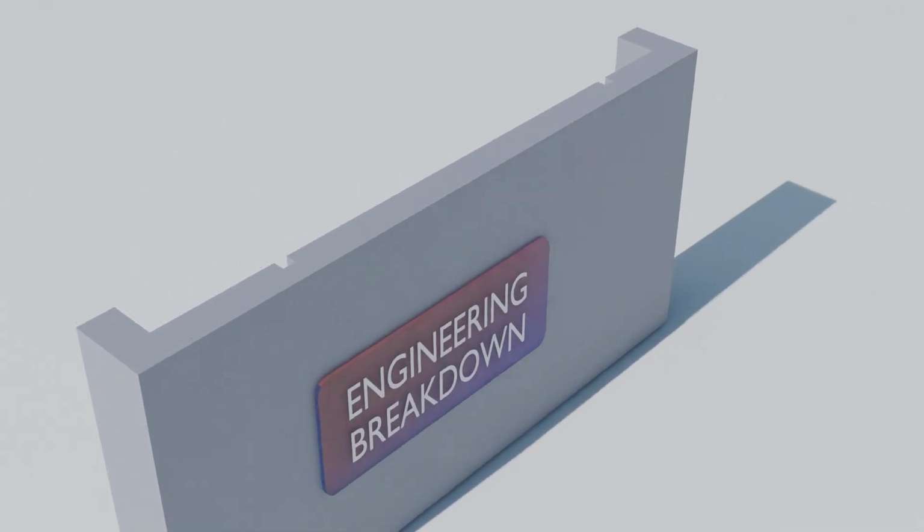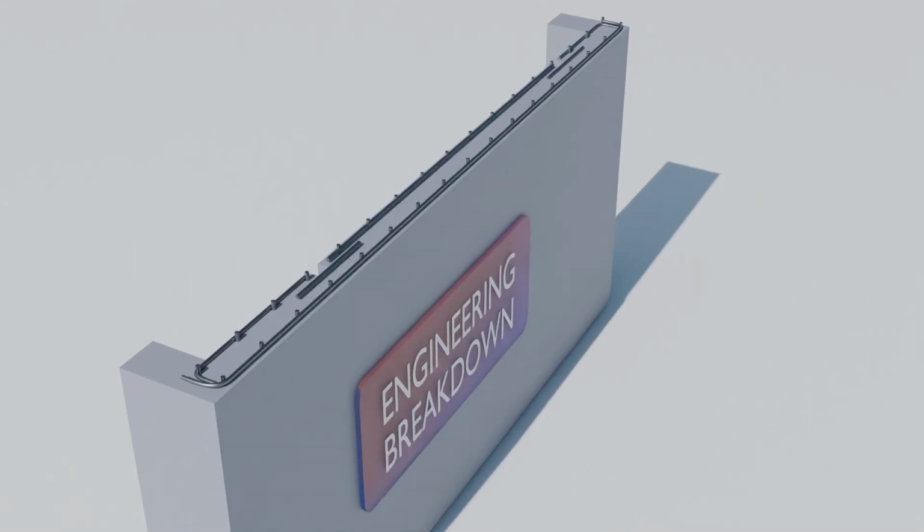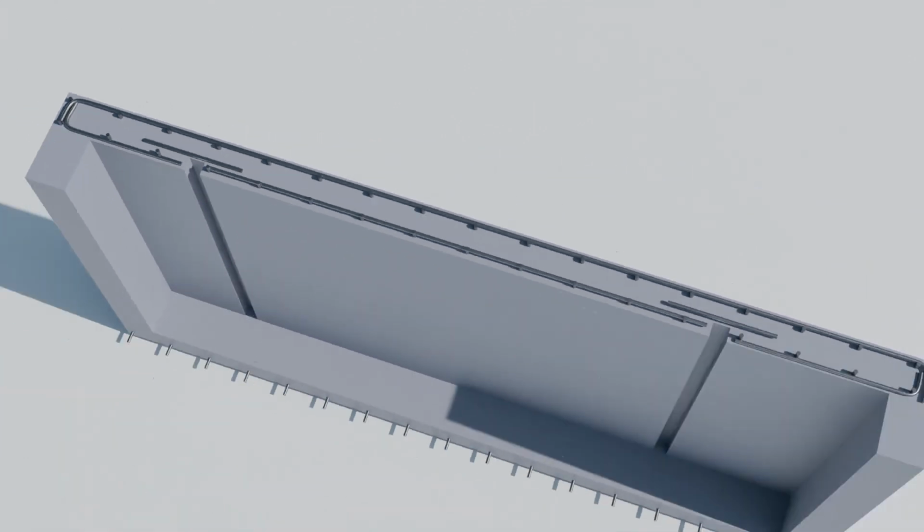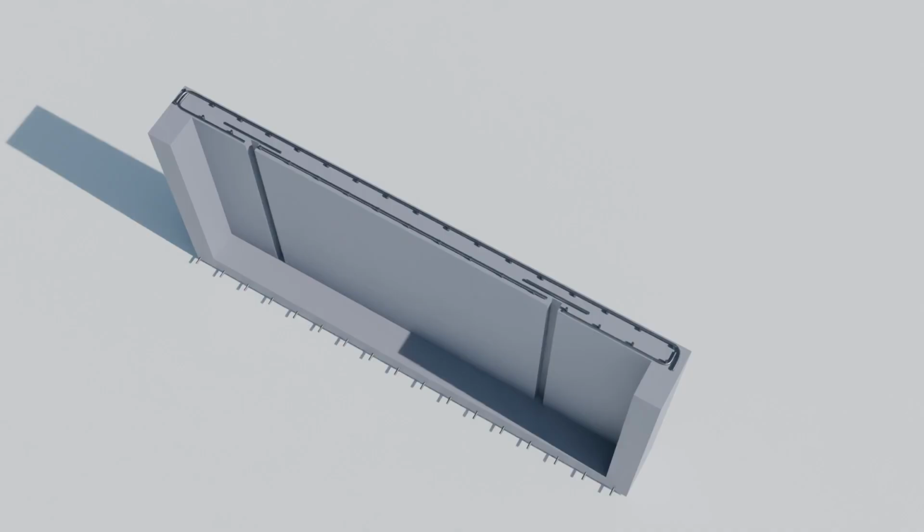For the wall, the story is similar. The reinforcement is arranged as per the shape of the wall as shown. The bars are curtailed at the indentations, or given 90-degree hooks, and secondary bars are provided at these indentations for countering stress. The overall wall reinforcement arrangement looks something like this.